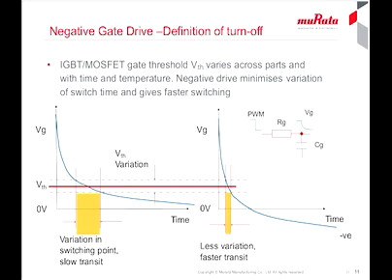Remember that the power device gate is like quite a large capacitor CG, and there will normally be some external gate resistance RG in the circuit. So even if the drive waveform has a very short fall time, the RC discharge effect of the resistance and capacitance slows it down at the gate connection at the semiconductor die. Sometimes this is designed to be slow to help with EMI.